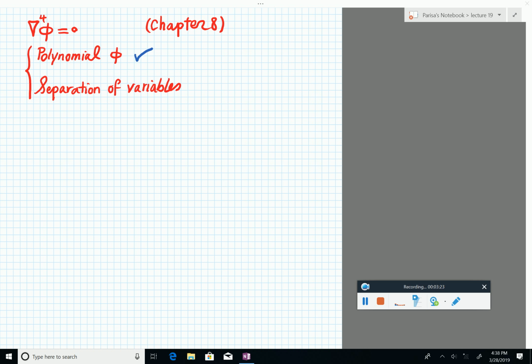When you assume that the stress potential phi is polynomial, what kind of a stress field did we always get, in terms of the kind of function? Yeah, because you take derivatives. So can you say that you can solve all the problems in elasticity using polynomial stress fields? Are the solutions always polynomial?